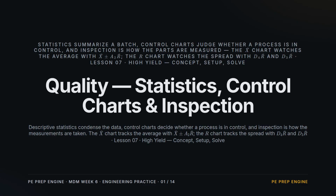Week 6, Lesson 7: Quality, Statistics, Control Charts, and Inspection. The exam asks 3 things here. Summarize a batch of measurements, decide whether a process is in control, and know how the parts get measured. We cover the descriptive statistics, build the X-bar and R charts from the sample size constants, run one full control limit problem, and close with the out-of-control tests and the inspection tools.